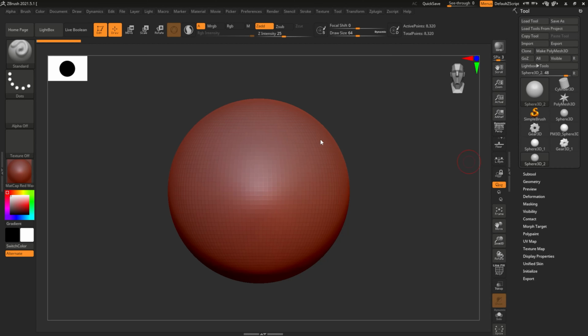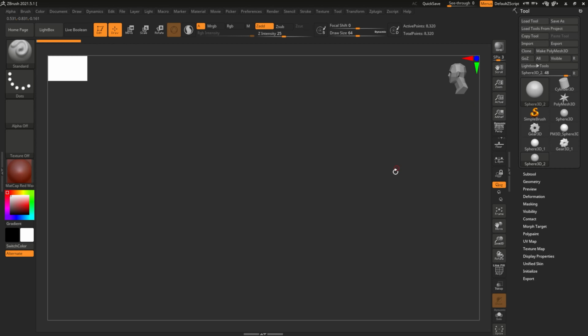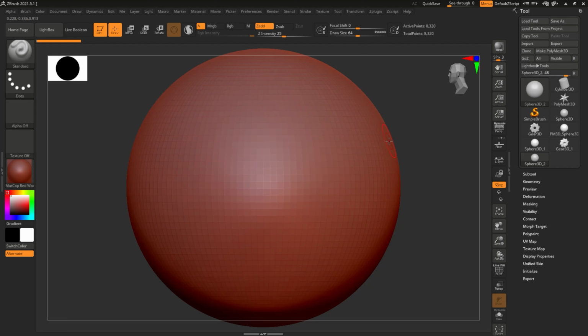This time, we will look at resetting the camera position in the UI together. Let's assume that the model has gone out of the screen, as if it has been taken out in this way. There are people who sometimes go looking for their model here. The shortcut key called Frame is F, and by pressing F, the model is automatically displayed on the screen. You can center it. This is a function that is often used during work, so keep it in mind.